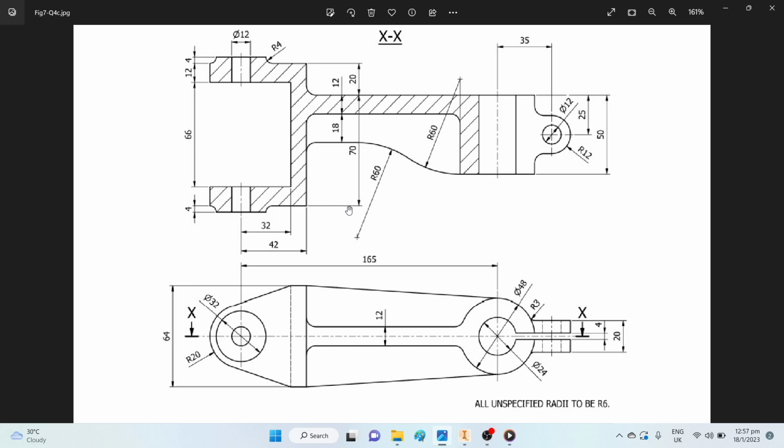For me, I will start off this drawing on the left hand side, and I will create this profile. I will draw out this profile, where the mouse is moving through, on an XZ plane, and I will extrude it up by 20, and I'll extrude it down by 70, so that I have a work plane that runs right across the flat of this part. Okay, now first up,